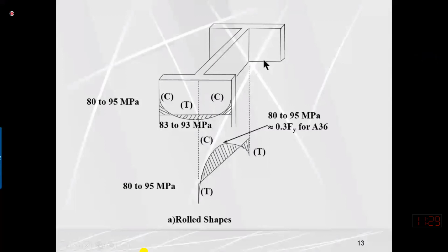When they cool down, all types of metal shrink. So the flange tip can shrink freely. But when the other part of the flange tends to shrink, during the shrinkage process it tends to move outward. This shrinkage tends to apply tensile stresses on the junction. So shrinkage of the flanges produces tensile strain on the junction.